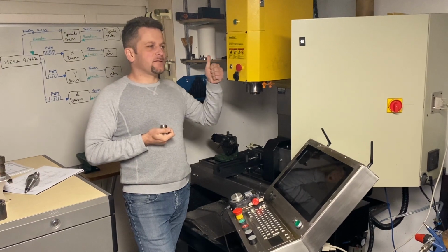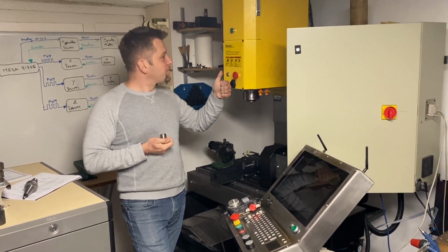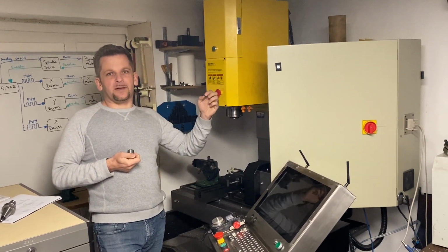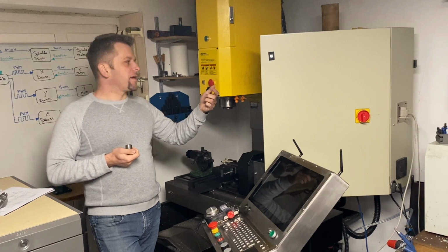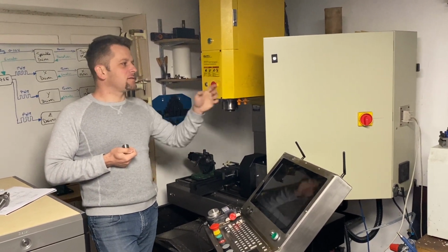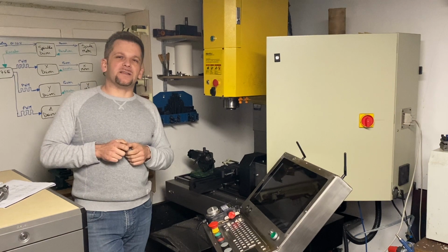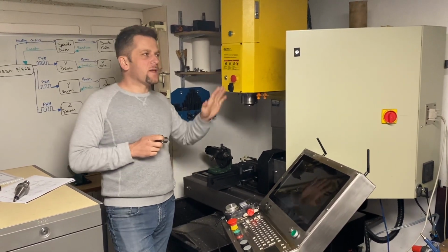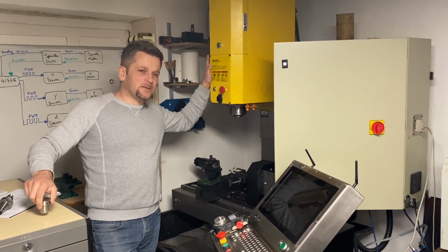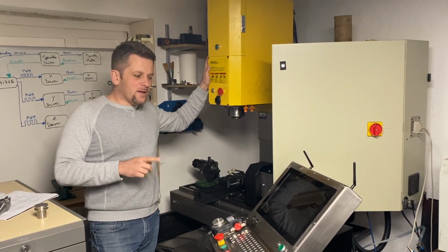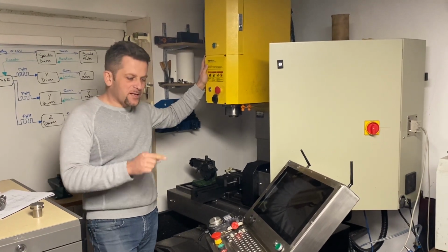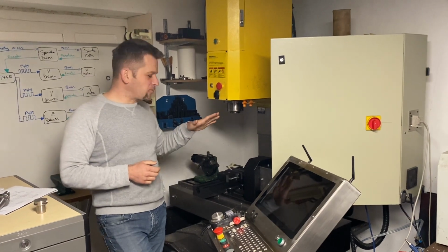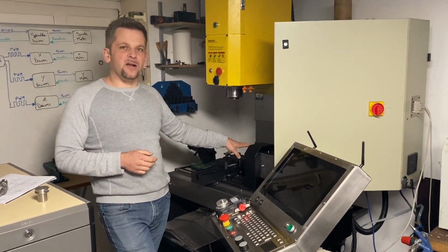the Z driver faulted and the spindle driver faulted. So I restarted the machine and wanted to do a homing. And at that point, I didn't notice that this was closed. I didn't notice that the spindle driver exited out of the fault, but the Z-axis driver was still in fault. So I hit home. On the display the machine was homing, but in reality it was not. So it was still stuck here.